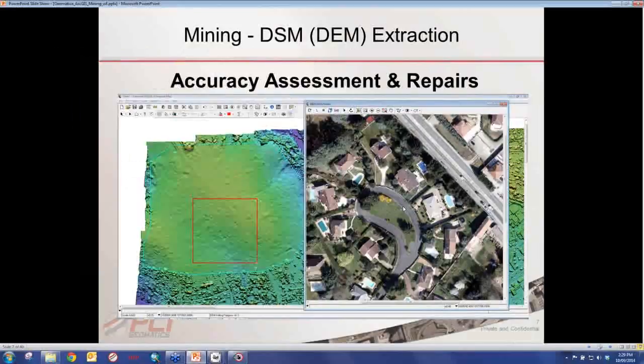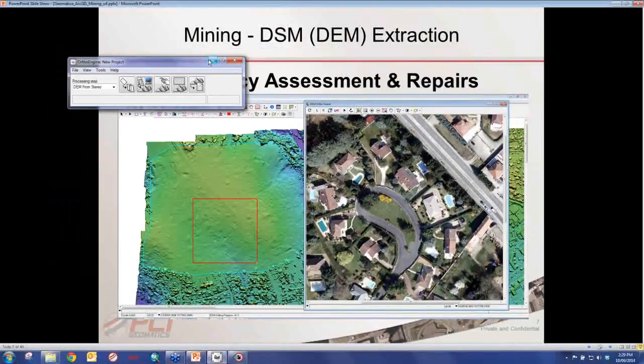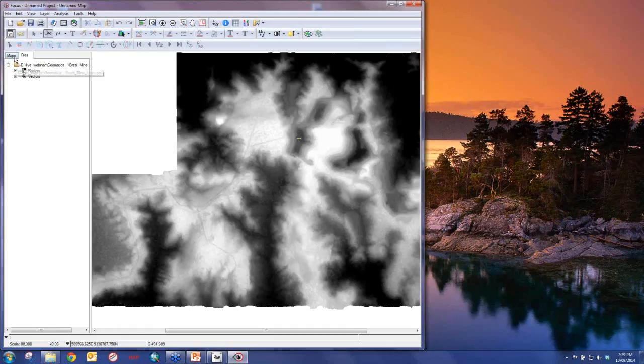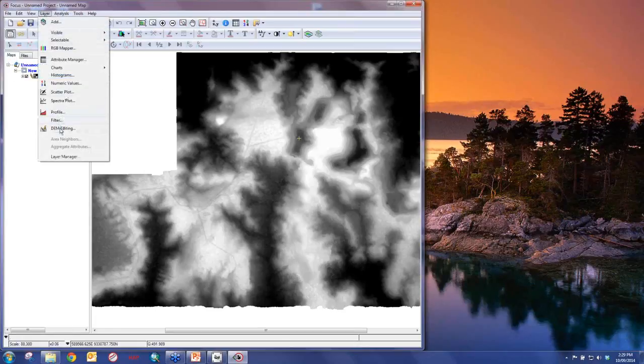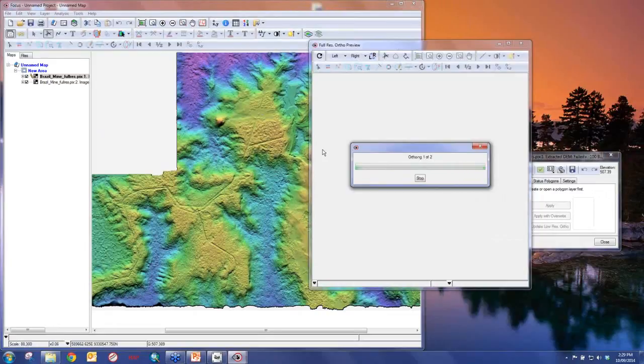And then what we should see is that if the elevation is accurate, surface features such as the grass here, the roadway, pathway, whatever it may be, and as we can see the DEM completed processing, they should be stable, whereas buildings and trees are going to move back and forth. So let's just lower that. So what we can do now is we can go to our area here, go to DEM editing, and we can draw a one-to-one window.